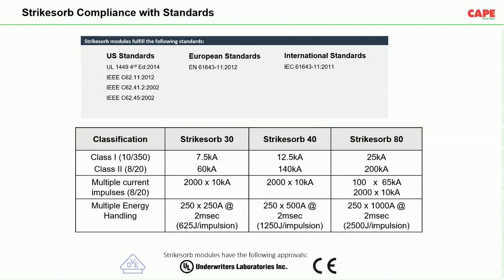Now, another important subject: normally a DIN rail mounted SPD is tested with a surge current, and then immediately the SPD becomes hot. The next test has to be carried out after cooling down the surge arrestor to its normal temperature.